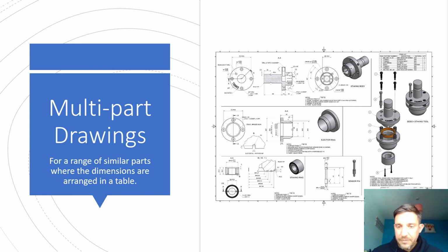So on here, if any of the dimensions are reused, so let's say there's a 20mm here, I could identify that dimension as A, and on this one I could dimension again 20mm A, and on this one A, and then in a little table I could have A equals 20mm. Okay, so it can share information, and it's basically because it's self-contained. It can make it easier.